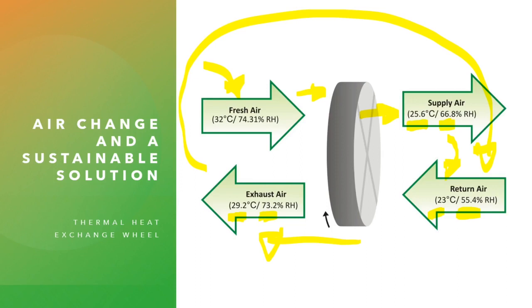So what we're doing here is as the energy comes in, we're cooling it down to the point where it's comfortable for us. But in a cruder form, when we vent hot air out of the classroom, let's suppose we're venting out 25 degrees and we're bringing in fresh air at say 15 degrees, perhaps we're bringing it from outside itself. Well, what the thermal wheel, or the heat exchanger, does, it traps some of the energy in the return air, bottom right corner, return air.